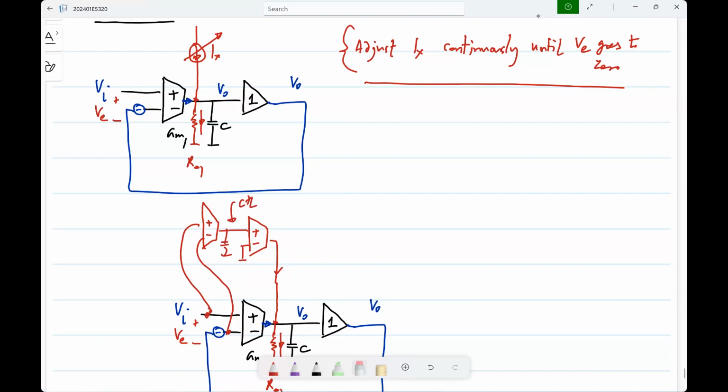Why will it not be ideal? Exactly. So now, of course, these GMs will also have their own output resistances. So that means that V will be some small value, but not necessarily 0. But it will be better than before. Now we can put our analysis machinery to work and then see what happens. So this is one more type of op amp, and this is of course quite different from